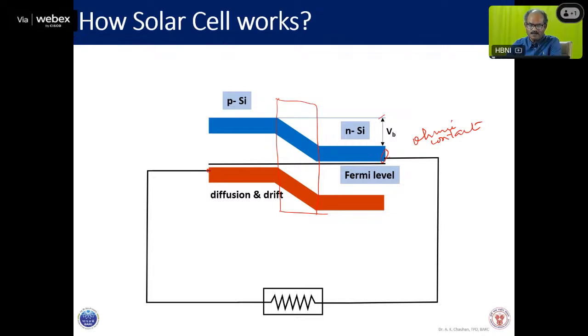What is a solar cell? Typically we can consider it as a PN junction, and light falls on the junction, and an electron-hole pair is generated, and these electron-hole pairs are separated. Why are they separated? Because there is a built-in potential. If there is no built-in potential, they will stay there and recombine. When will they recombine? What we learned yesterday, there is something called the lifetime. So up to their lifetime, they will remain in the excited state, but ultimately they will recombine, and there are two kinds of recombination only. This also we learned yesterday.